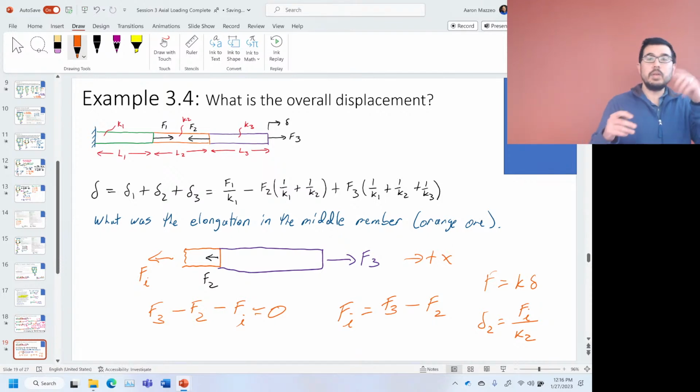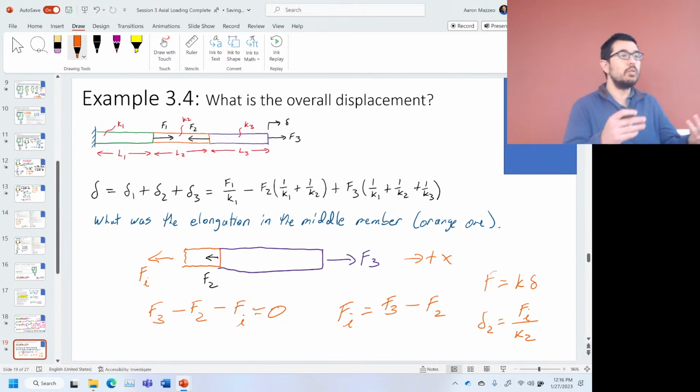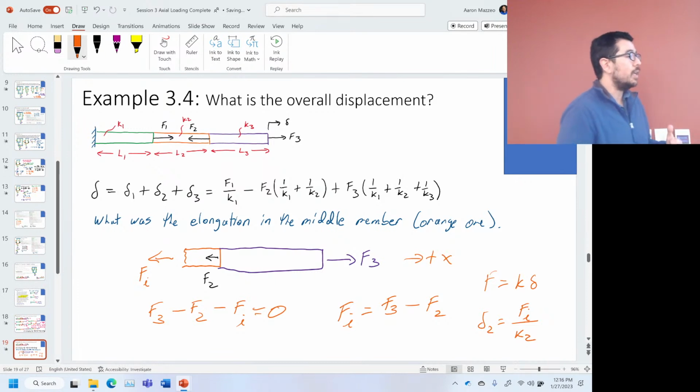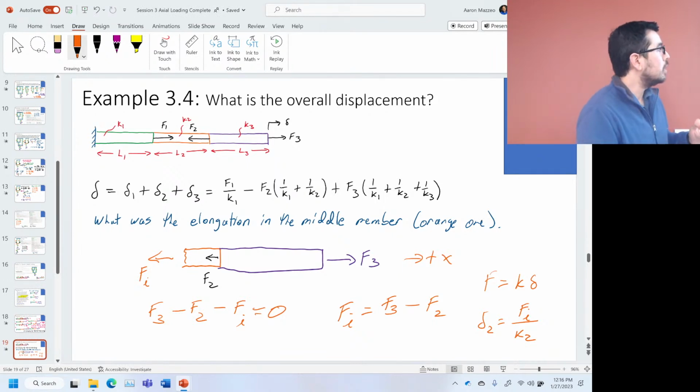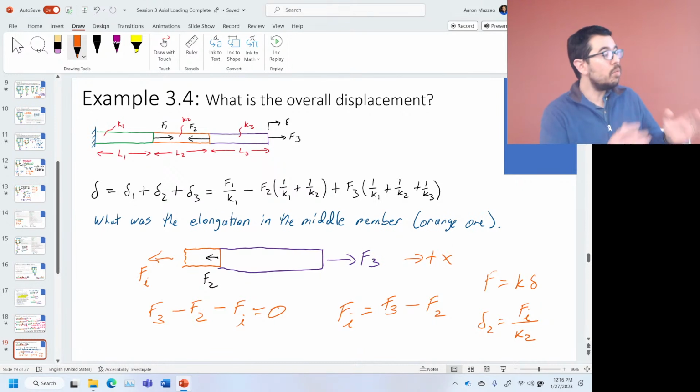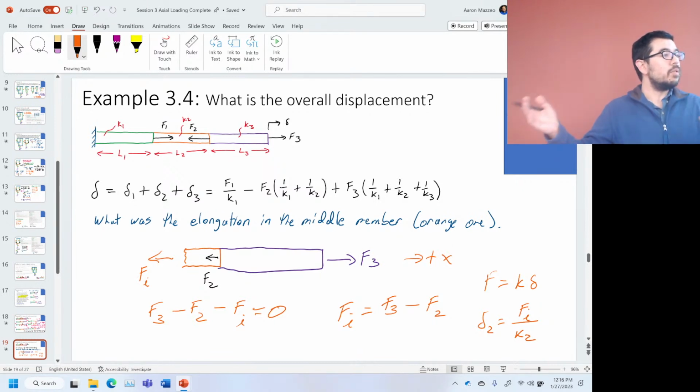When we're doing deformation, we need to make sure that we're performing equilibrium. If you want, go back to the notes on, I think it was session 2, where we did static equilibrium. We first want to look at external equilibrium on the system, and then we do a cut. In this case, I went right at it. We have an external force here and here, but I'm able to do a cut. If you wanted to, you could leave the right side exposed.